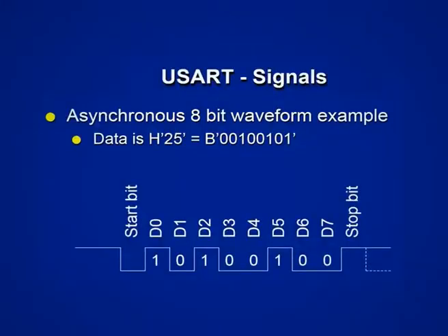By design, this is an inefficient protocol because to send 8 data bits, we need to send one start bit and one stop bit. At the receiving end, start and stop bits are stripped off and only 8 bits are sent to the host computer. Thus, out of 10 bits sent, only 8 bits are used and hence efficiency is only about 80%.